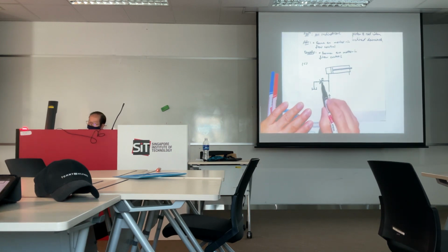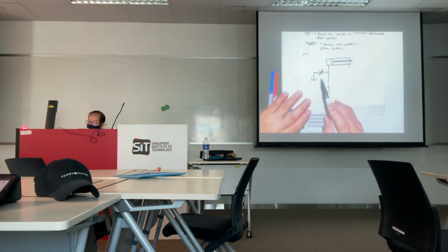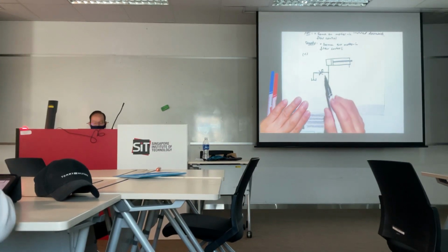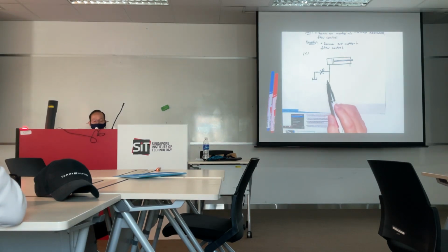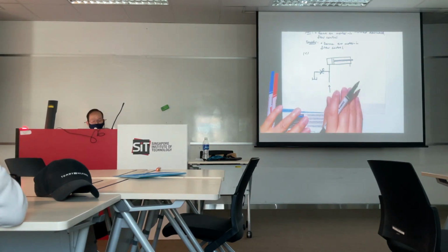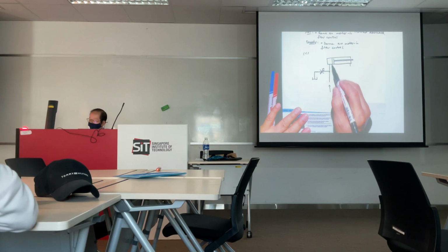So this orifice can open to be quite big, not as small as the throttle check valve orifice, which is very very small. This one can open to be quite big, up to whatever flow rate you want to bleed off. So again, this is almost like meter in flow control because you're controlling the flow rate that's going in.